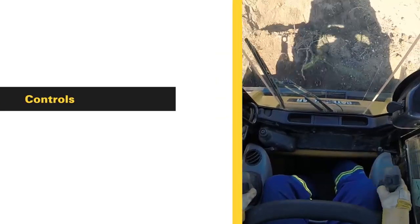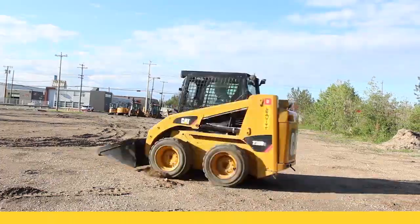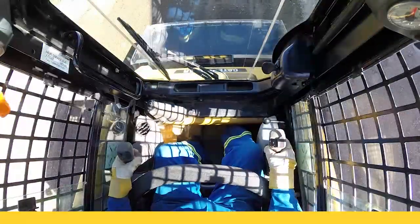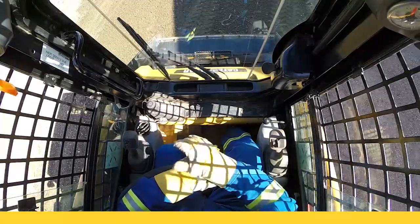Controls. For novice skid steer operators, the multifunction features on skid steer loader controls can be confusing. Because skid steer loaders react immediately to very little hydraulic pressure, novice operators need to understand the requirements for delicate operation and when to take their hands and feet off the controls.